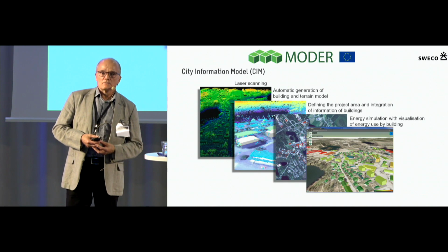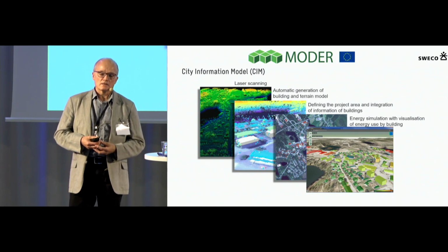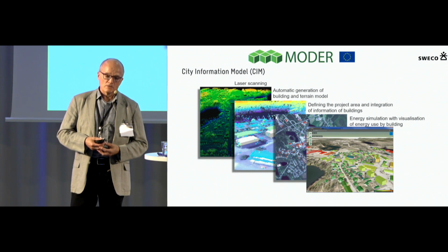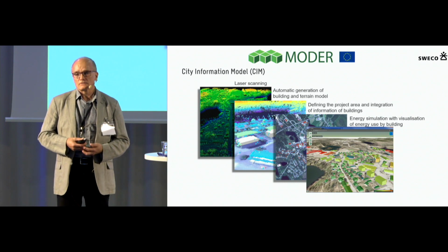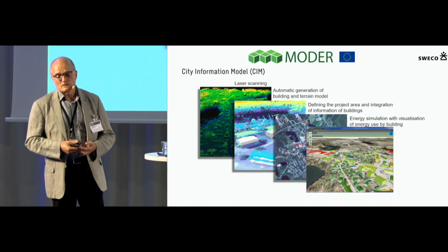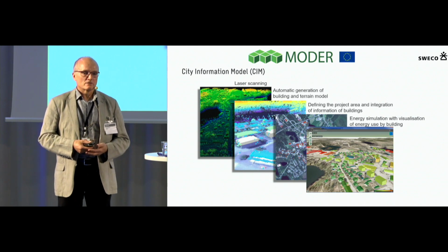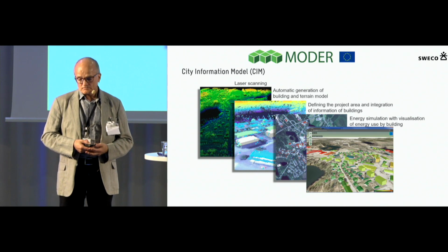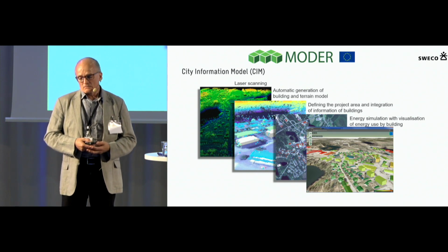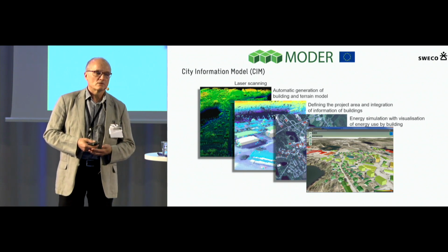This is not very difficult to do if you have the laser scanning data of the area. You can just use the point clouds that the scanning is creating, and you can get the locations of the buildings and right dimensions for the buildings. And then if you have it somewhere in the cloud, everybody can also add the information into the system. You can do it by drone nowadays. I think that you don't even have to have an aeroplane or a helicopter to do it.